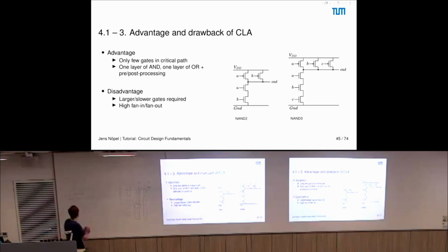Great question, yeah? So what happens now if the input toggles? So it goes from 0 to 1, for example. If it goes from 0 to 1, then this one was open and closes, and this one starts to open. But this means now that this one is closing not as fast as this one is opening. So this means that switching from 0 to 1, this one is a lot faster, right?